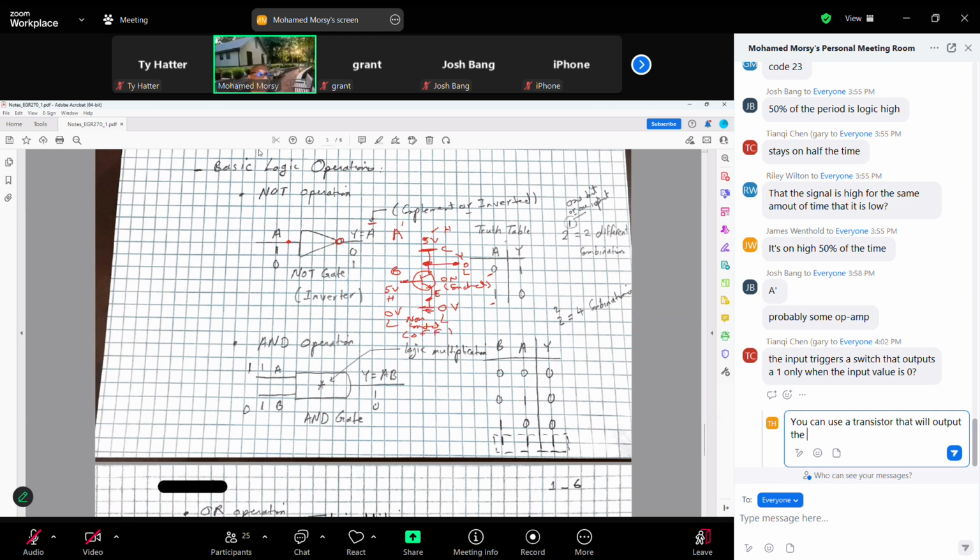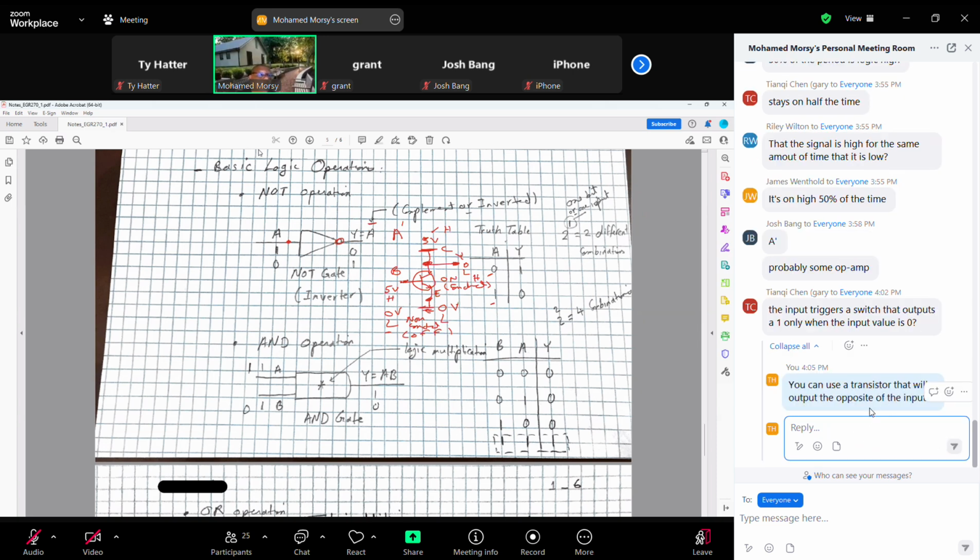What is meant by off? It means this point is not connected to this point. So this output takes the voltage directly from here, and now this gives us high here for this case. So we have 0 here, we have 5 here, or bit 0 and bit 1. This is a very simplified circuit to just show you what happens inside this symbol. This is how we got the input inverted as the output